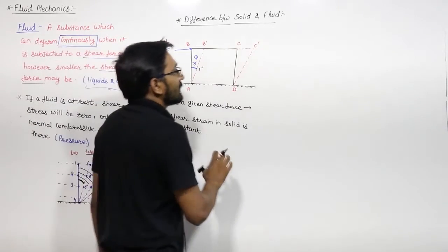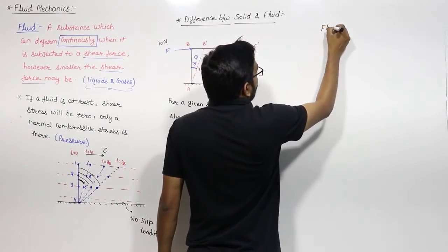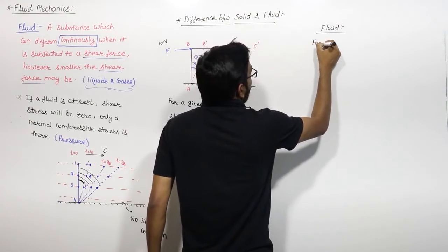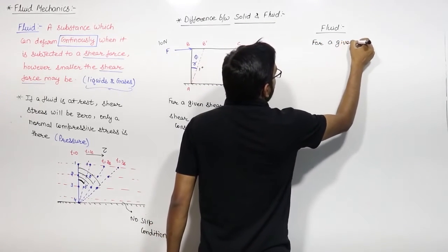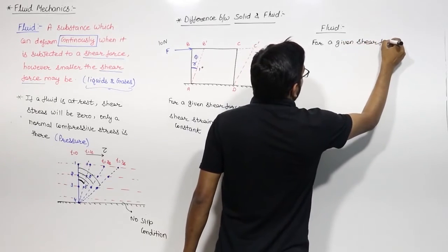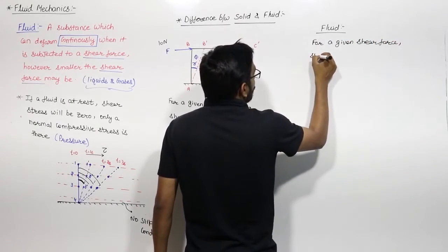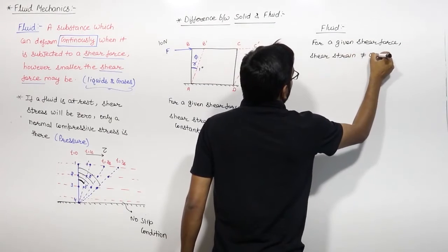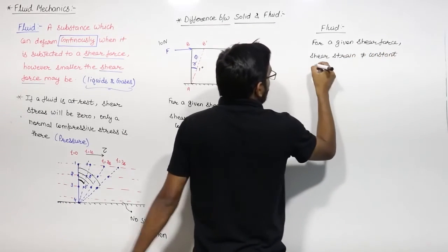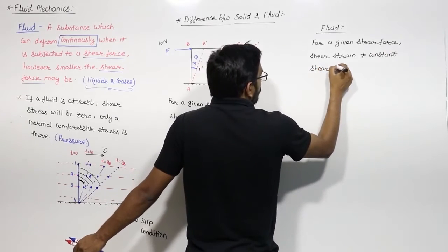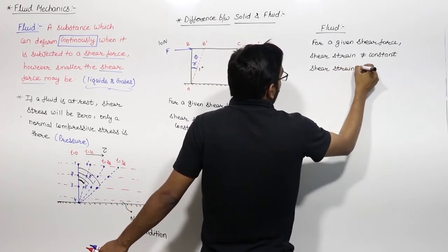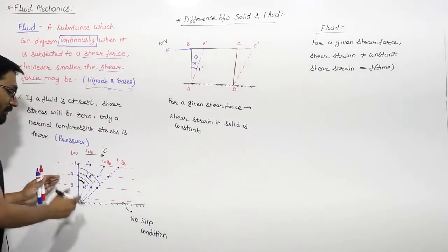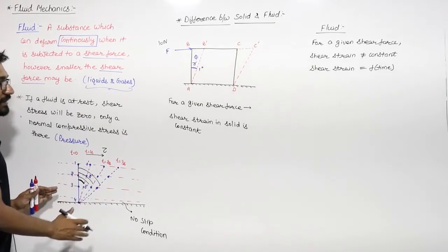But this is not the same for fluid. For the fluid, for a given shear force, your shear strain is not constant. You can see from here that in the fluid, shear strain under a given force is a function of time. As time increases, this angle will increase.